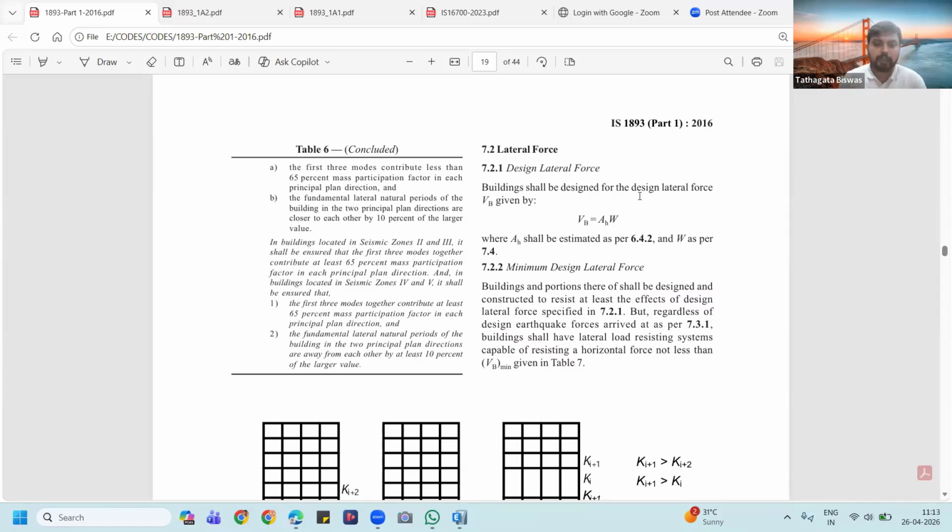Okay, that is incorrect, because that particular wall material will also give us certain kind of lumped mass during the course of an earthquake. Lumped mass means what? It will also contribute to lateral forces. Okay. So how do we capture the effect of the stiffness of those walls? We do not know how much stiffness they will offer.